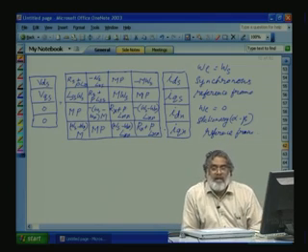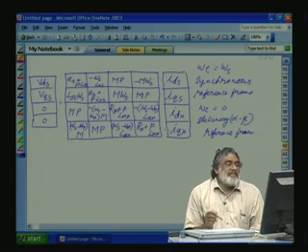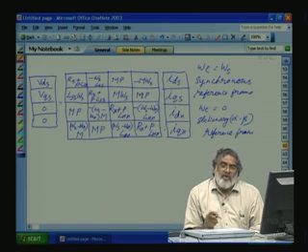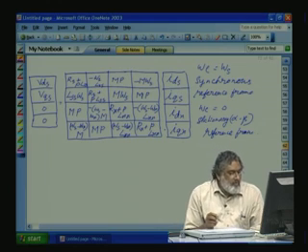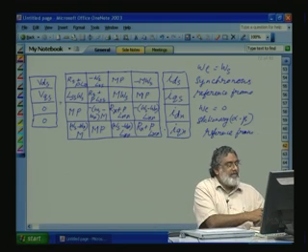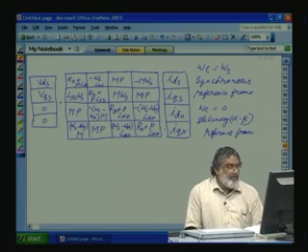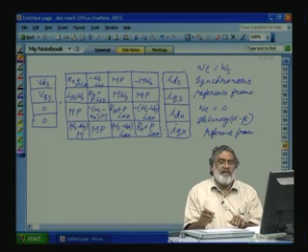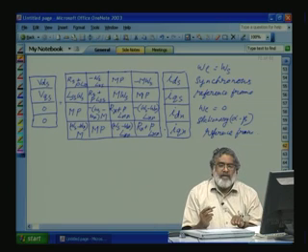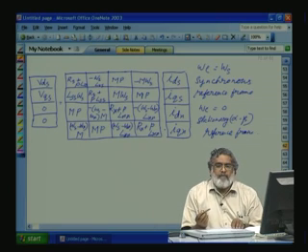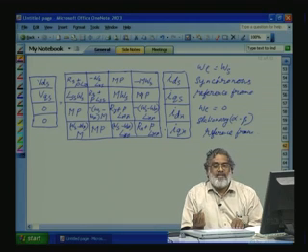We got the machine dynamic voltages in matrix form. Here, we can either use the equivalent circuit or this one. If you see here, what is the torque produced? The torque produced is power divided by the frequency of operation, so torque is power divided by the speed. Power means voltage into current. The voltage responsible for the torque is the rotational voltage, because of the rotation we get the torque. So all the rotational voltages multiplied by current give the power which is responsible for the torque production.